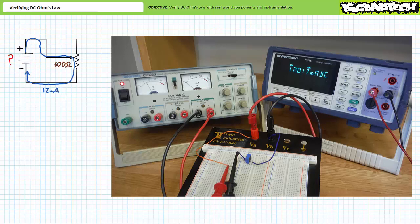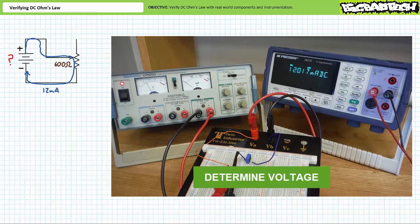Resistance stayed the same and current increased. Did voltage go up, go down, or remain the same? If you're tracking, you should realize that voltage must have increased. As an exercise to the viewer, I invite you to calculate the voltage necessary to induce 12 milliamperes of current to travel through a 600 ohm resistor.